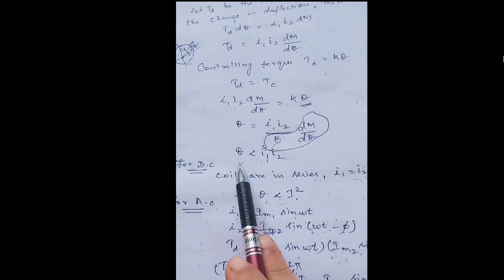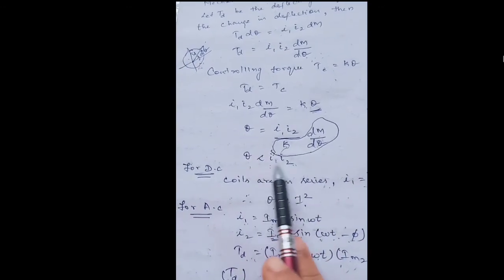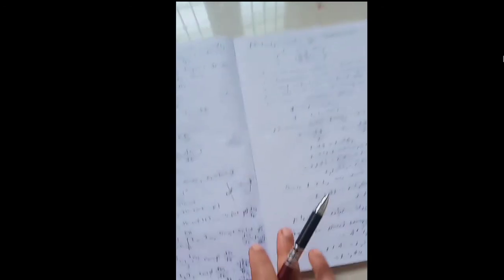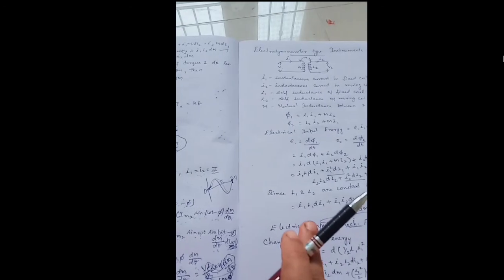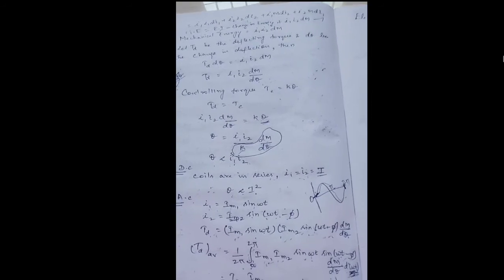Apart from measuring currents by equating it directly with the currents, we can also measure the power in an AC circuit using the same instrument with a little bit of modification in the circuit. So these electrodynamometer type instruments are meant for measuring the AC as well as DC values of currents and voltages, and the major function of this electrodynamometer type instrument is for measuring the power entering a circuit. So this is about the torque equation.